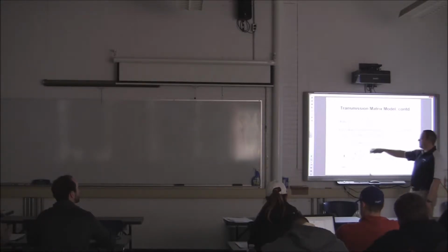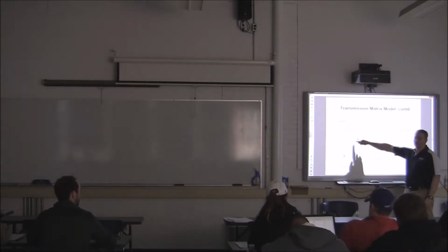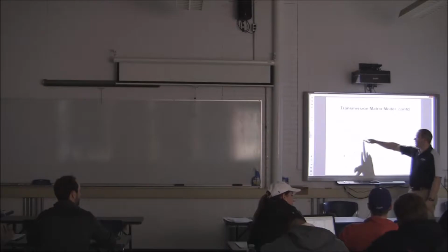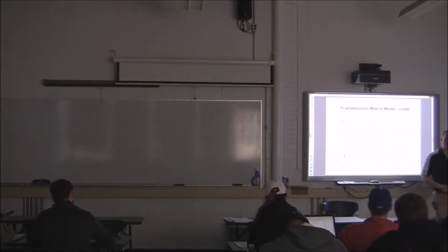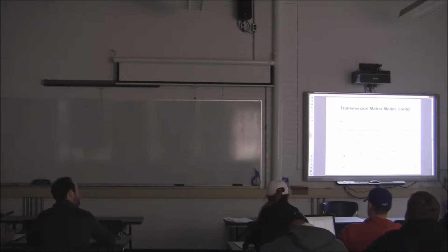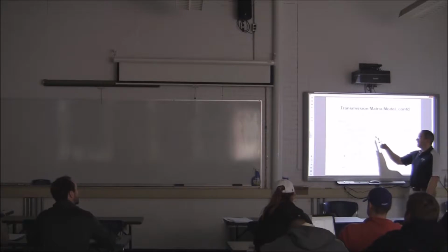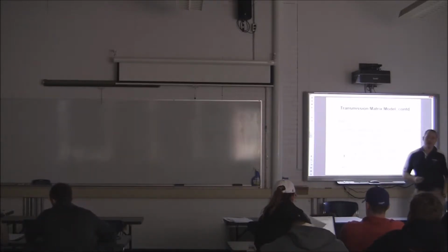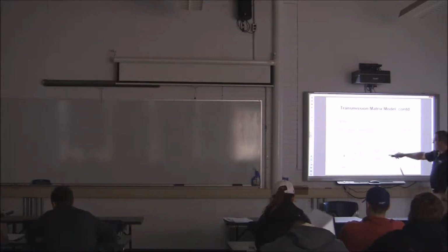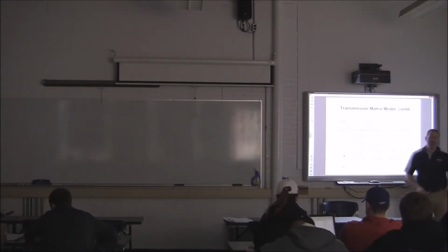So in our very basic form, if we just steal these equations, well, we can say what times VR equals Vs. Well, this is hyperbolic cosine of gamma L. So A is just hyperbolic cosine of gamma L. B is ZC, with IR pulled out, right? Hyperbolic sine of gamma L. That's my B term. I keep going with C and D.